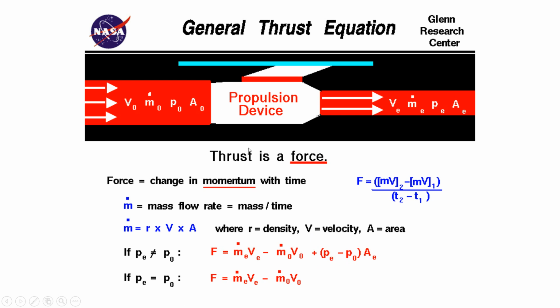So with that, like we discussed, it is given by mass flow rate into exit velocity minus inlet velocity. Sorry, I said ratios of mass flow rate; no, it is just mass flow rate into difference in velocity. And we know mass flow rate of output is an addition of fuel, but fuel ratio is very small, so we'll take it as 1, and that will ultimately come to mass flow rate into velocity exit minus velocity inlet.